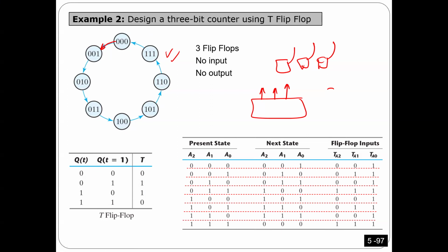Right? So if you look at the circuit here, you can see in the very beginning I have 0, 0, 0 because you have three outputs. This generator has 3 outputs. After 1 clock, it becomes number 1. After 1 clock, it becomes number 2. After 1 clock, it becomes number 3, all the way until 1, 1, 1. Sorry, 3 ones. After 3 ones, you are going to regenerate the sequence again.